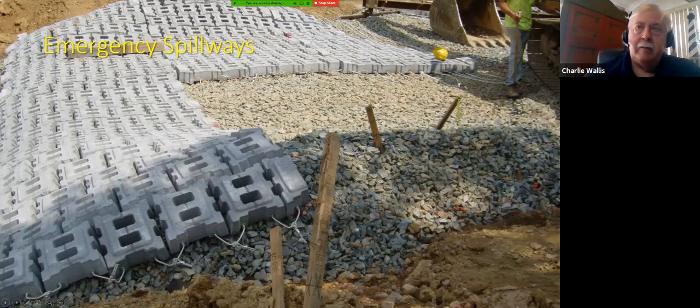We talked about auxiliary or emergency spillways. These are on native ground, and typically they're just grass covered. And this is the case here. It was envisioned that there were going to be flows with high velocities, so articulated concrete block is being placed on it, which will withstand the force of those flows. But you can see a variety of different surfaces on these spillways.